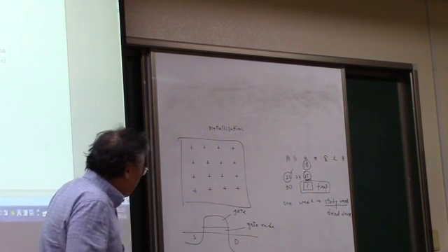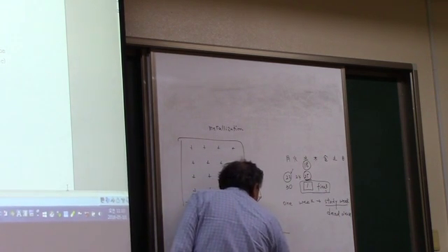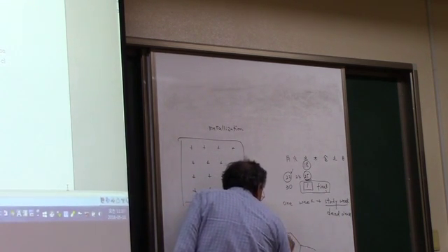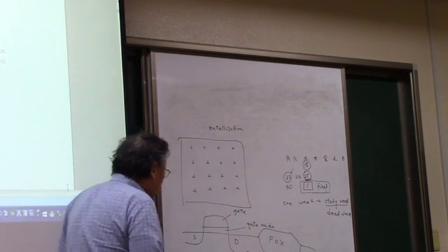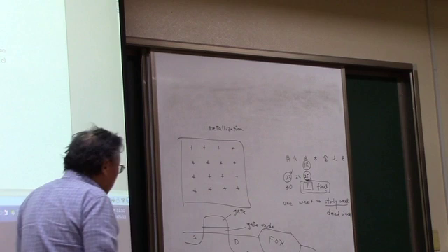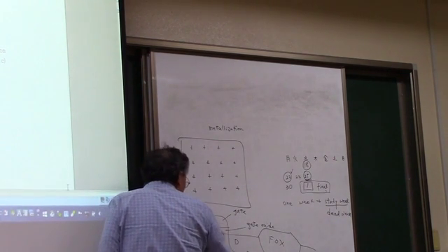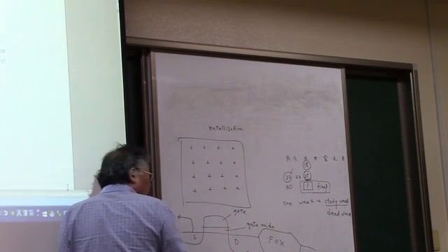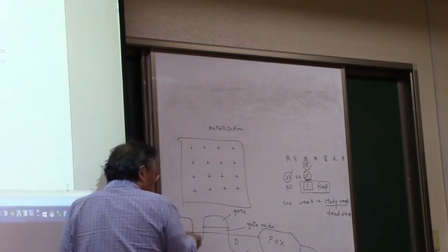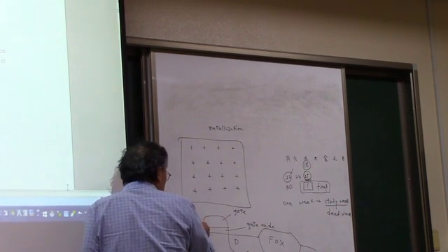All right, and then this is separated from other transistors with field oxide, the LOCOS process that we have discussed. And then after this, a transistor source and another transistor drain or gate or source should be connected to form a circuit.